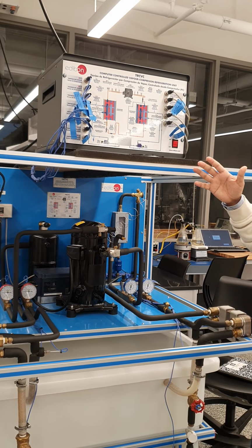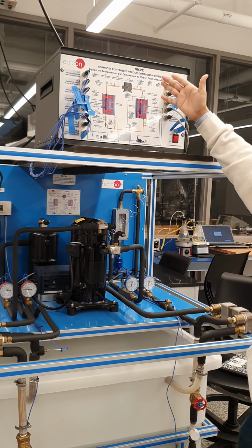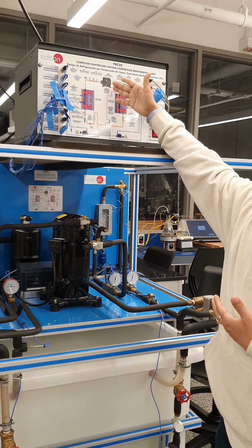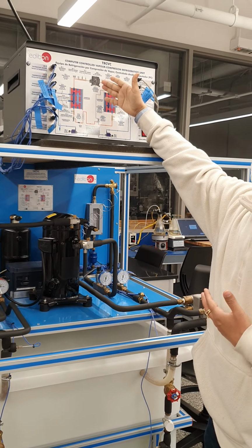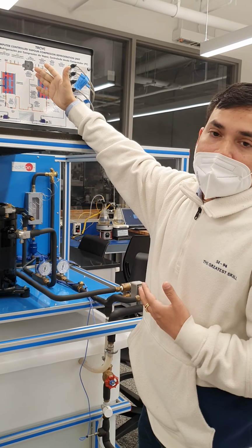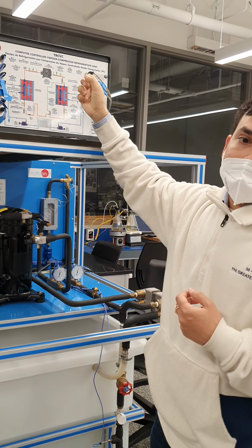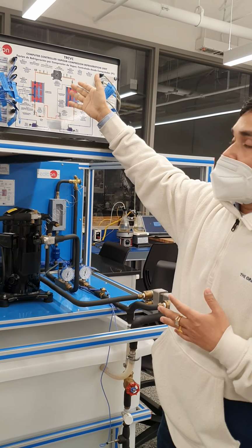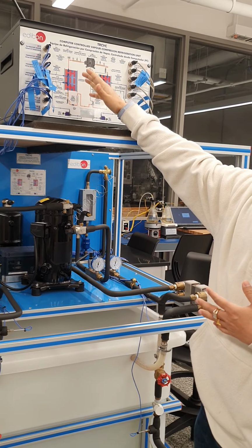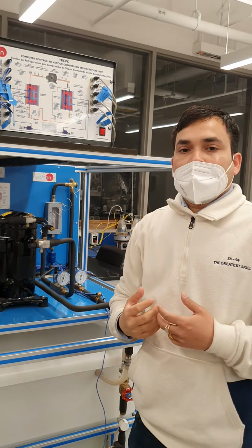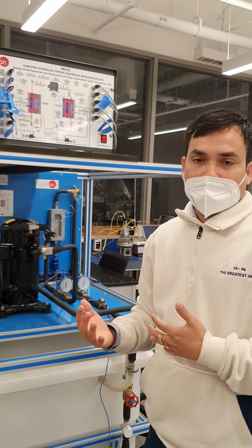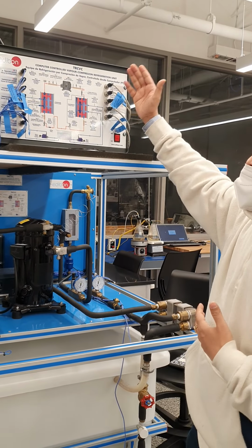If you go through the basic schematic diagram again, in this compressor, low temperature and low pressure vapor refrigerant is compressed, and after that it becomes high pressure and high temperature. Then it's delivered to the condenser. In the condenser, the high pressure and temperature vapor will change phase from the vapor phase to the liquid phase. After that it passes through the expansion valve.